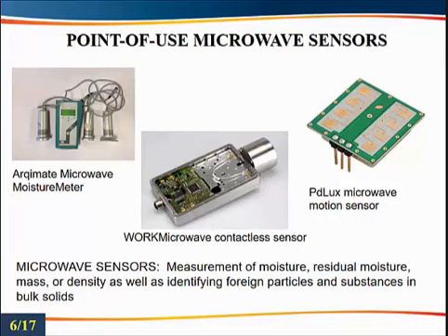For chemical variables, not so much, the reason being that microwave sensors at their heart are really just permittivity sensors. They sense the changes in the local permittivity in and around their environment, and that doesn't give you too much selectivity. So I'll talk a little later in this talk about how integrating nanomaterials with microwave resonators can give you that selectivity.